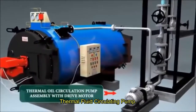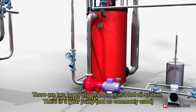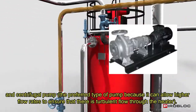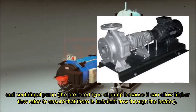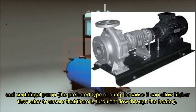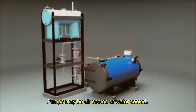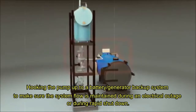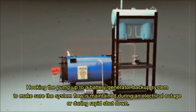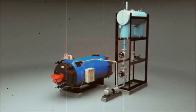Thermal fluid circulating pump. There are two types of pumps used in a hot oil system. There is a gear pump, not as commonly used, and the centrifugal pump, the preferred type of pump because it can allow higher flow rates to ensure that there is turbulent flow through the heater. Pumps may be air-cooled or water-cooled. Hooking the pump up to a battery or generator backup system makes sure the system flow is maintained during an electrical outage or during rapid shutdown.